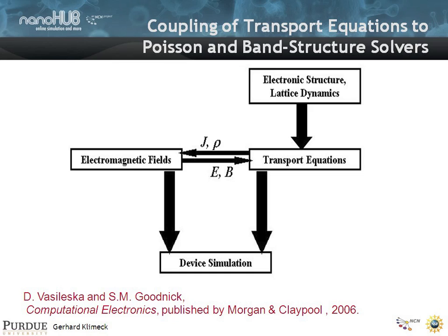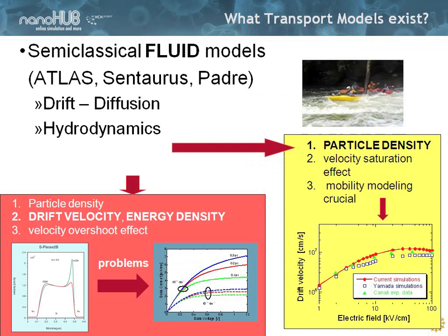And what you end up doing is you couple the electronic structure and the lattice dynamics to some transport equations, and they are coupled to electromagnetic fields, and they're coupled to the device simulation. So this is a core element of most device simulation engines, that they have these components.